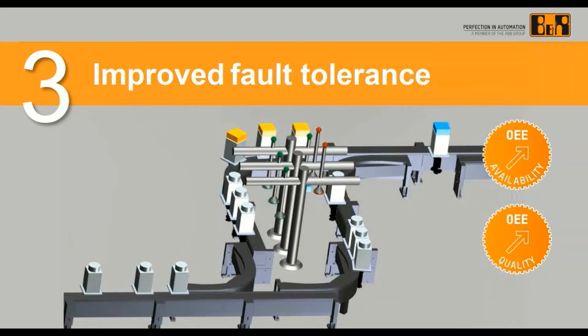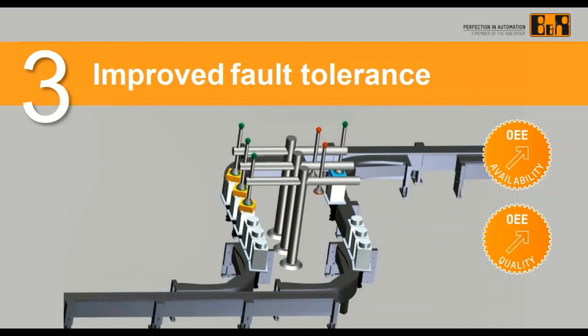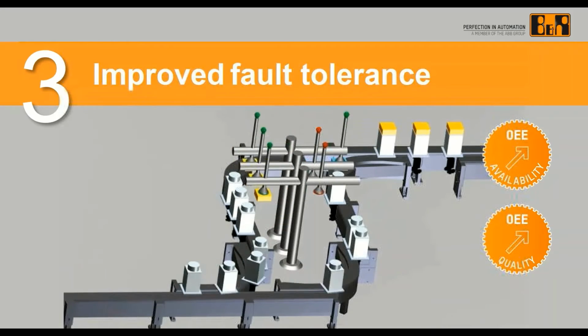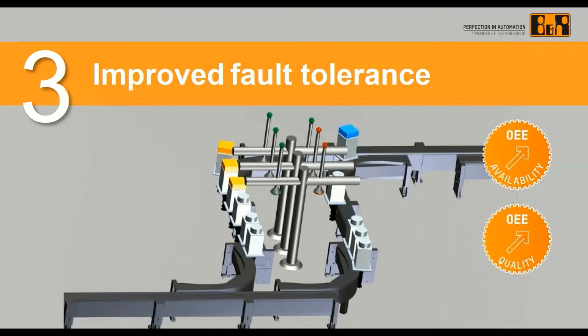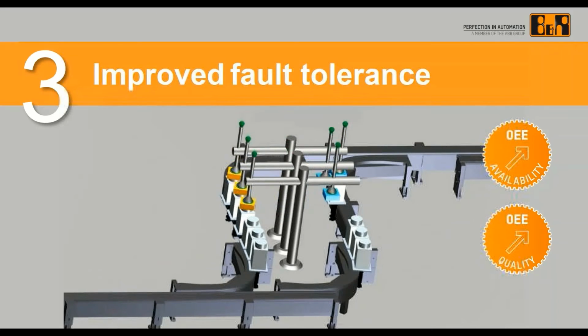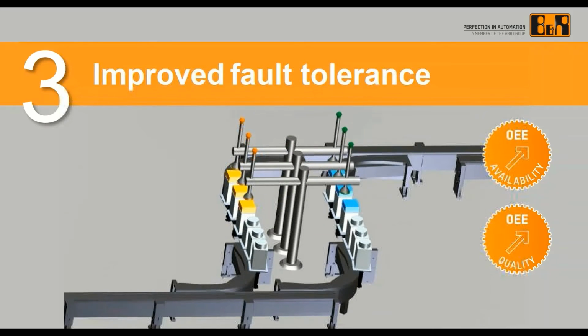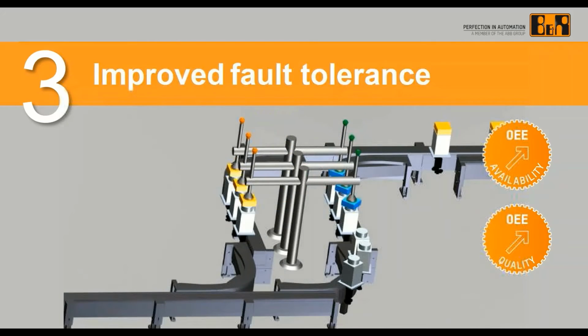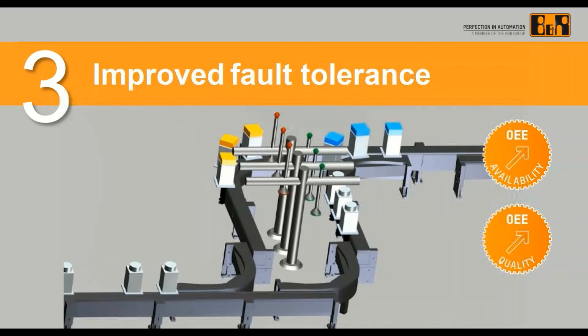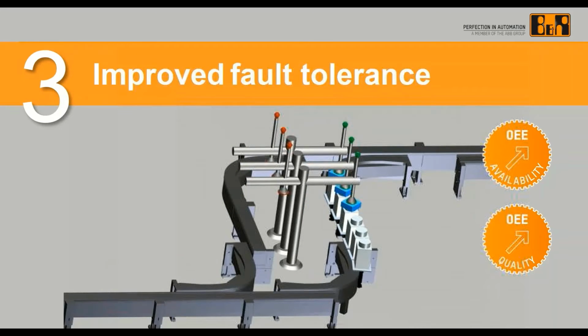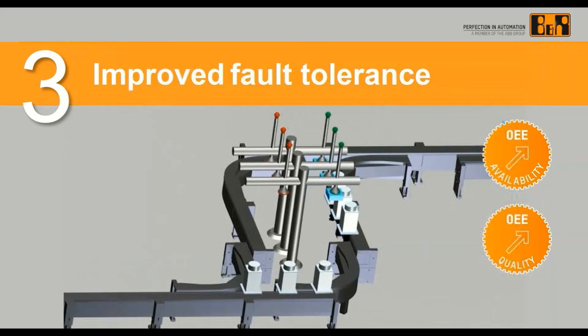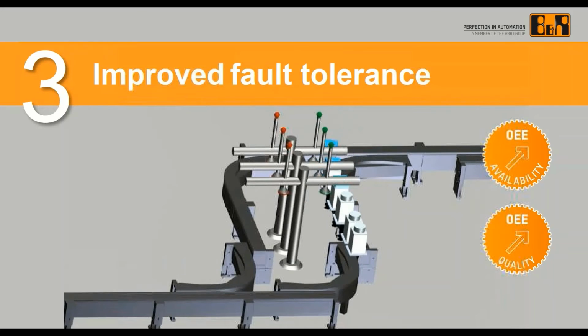In a typical conveyance system, for example, a feed screw, you wouldn't be able to do that. You'd have to continue to populate every position in the capping application, which means you'd be wasting product, wasting bottles, wasting caps, and then having to rerun all of the bad products back to the beginning. With Track, we can change that on the fly and simply omit a single section, a single station of the process.